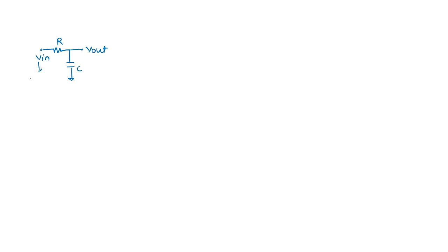So what we have applied in the second case, the frequency is very high to large. So it is shorted. Shorted simply means the output is zero. What we have seen for F equal to zero, my output was equal to input because no current was flowing. When F is very large, infinite, my output is nearly zero or exactly zero.